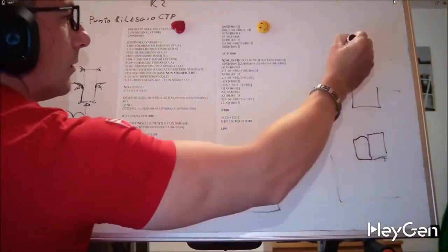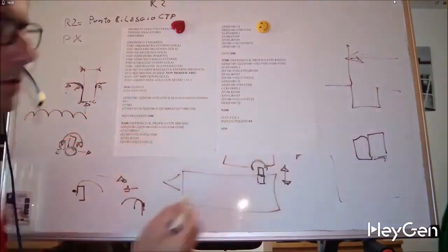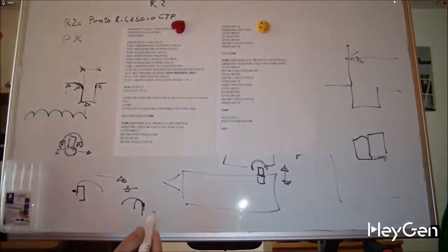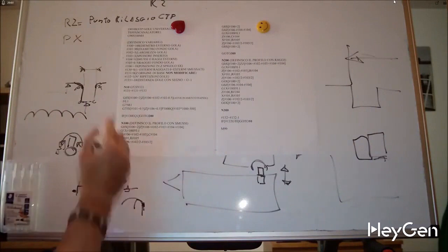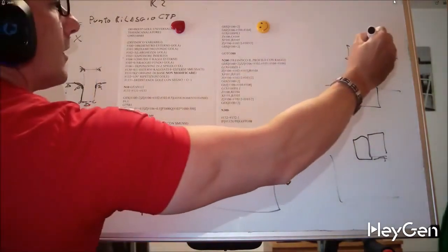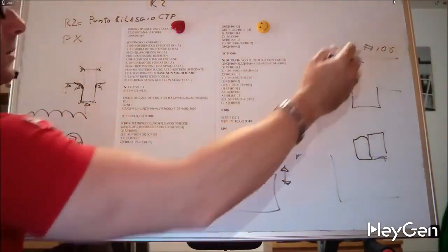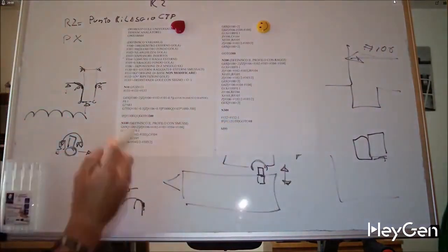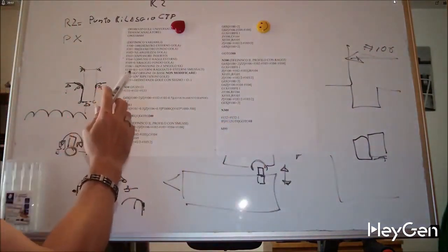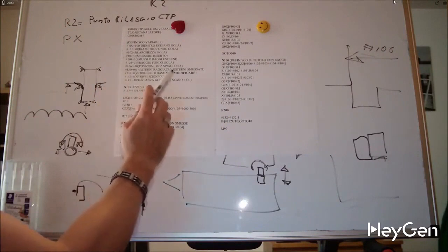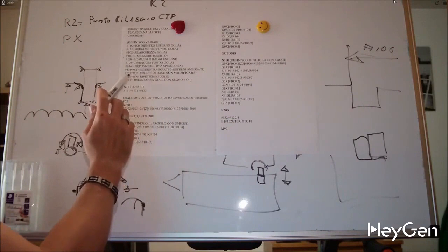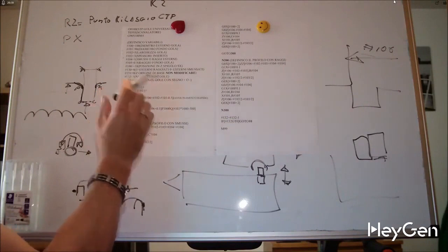The Z position of the left edge, this Z. I need to know where my groove is located. So this is percentage. And I always say percentage hashtag 106, 130. I have 0 for the chamfered outsides, and I put 1 for the radiused outsides. 0 is not to be changed. It's the base origin of my workpiece.